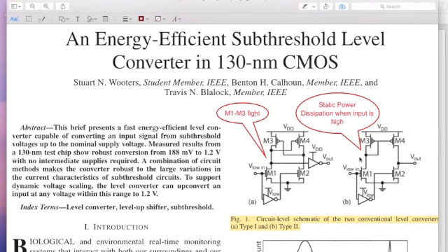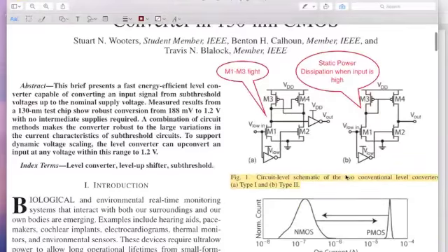So you have two devices on, M1 and M3. Of course, M1 is on weakly in subthreshold, but still you have a static power consumption in this line. That is why this is not such a good design from a power consumption perspective.